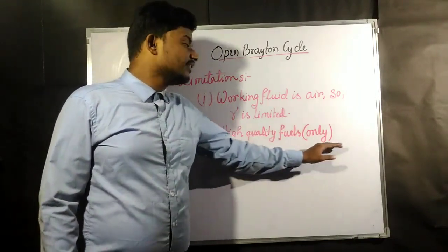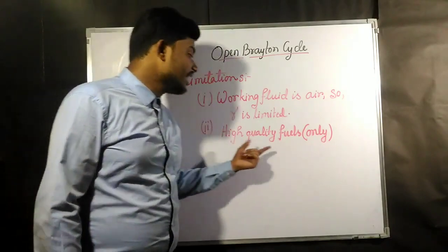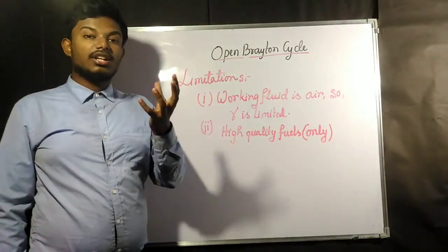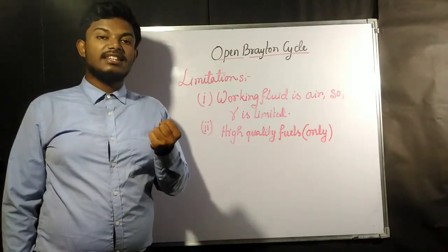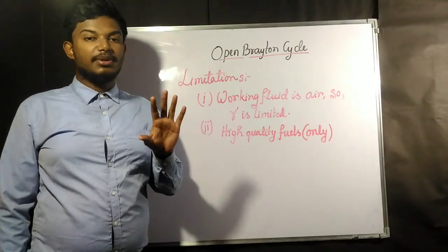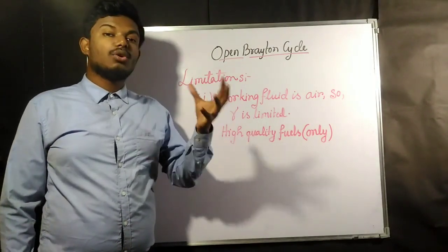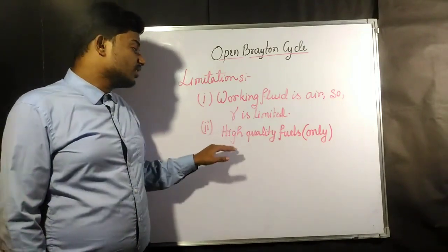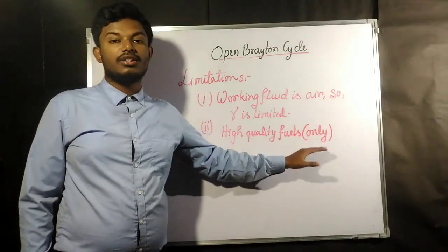The second thing is that it is going to use only high quality fuels. Why? Because the combustion products of the air fuel mixture go directly into the turbine. If they go directly into the turbine, that means corrosion or erosion may take place in the turbine. So only high quality fuels are going to be used.